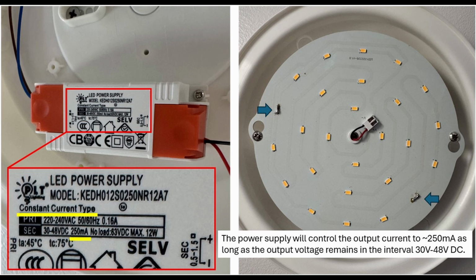So I started troubleshooting the LED plate, and just using a simple multimeter running for continuity, I could run a small current through each LED and see a very, very small light in the LED, which indicates that the LED is operational. So I removed the two LEDs that I found faulty.